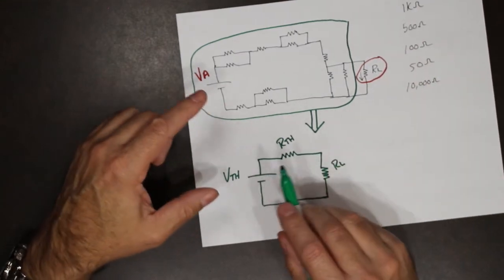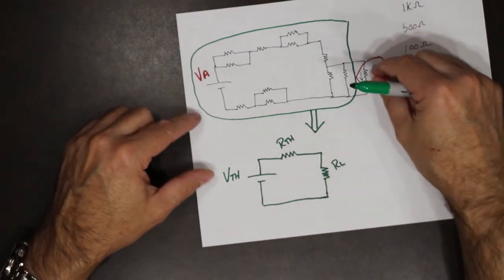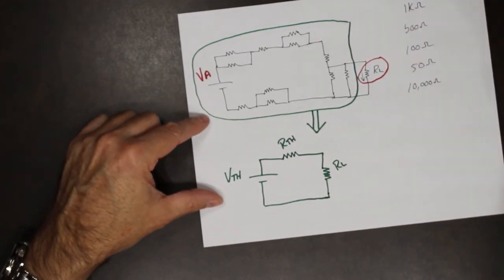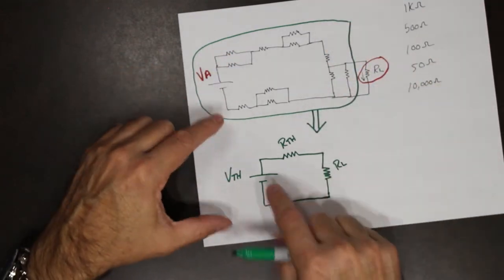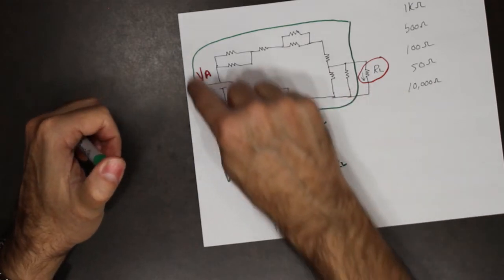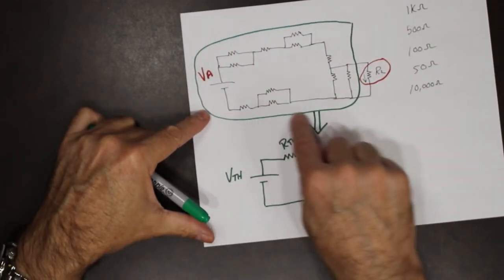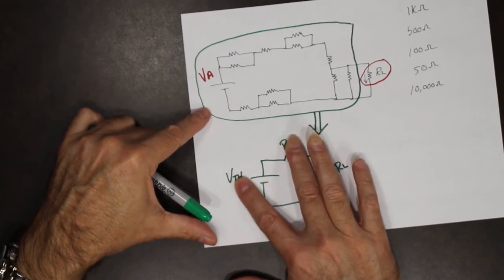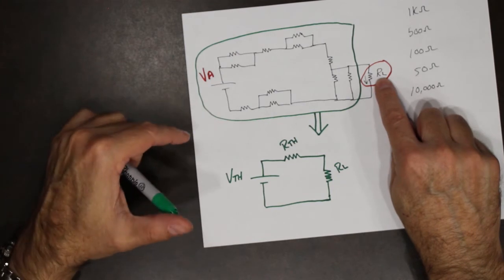These two values will always calculate out to be the same. I remove this resistor and then calculate for the rest of the circuit. So everything that's in that green circle square there is these two values. They remain constant even though I'm going to change the load.